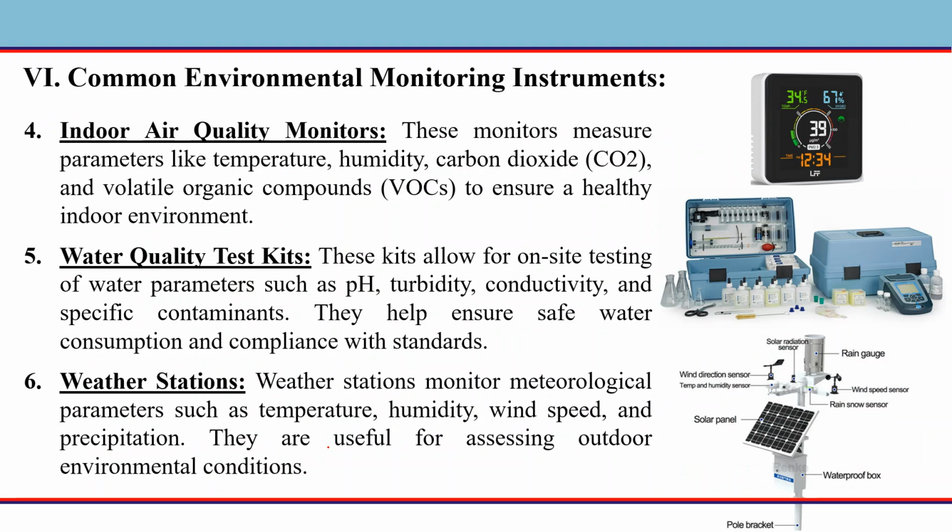Then we have indoor air quality monitors. These monitors measure parameters like temperature, humidity, CO2, volatile organic compounds to ensure a healthy indoor environment. Then we also have water quality test kits. These kits allow for on-site testing of water parameters such as pH, turbidity, conductivity, and specific contaminants. They help ensure safe water consumption and compliance with standards.